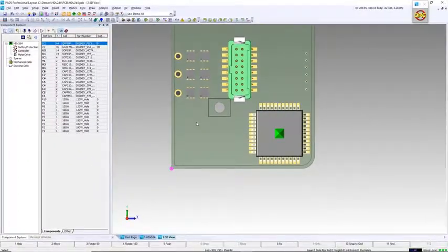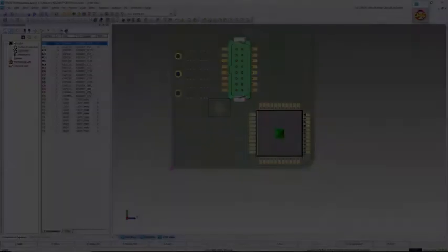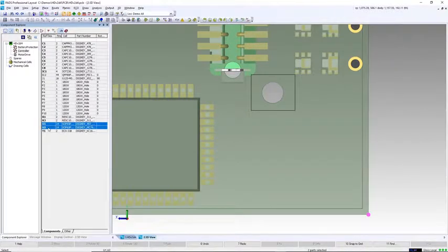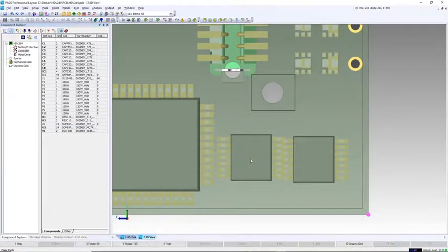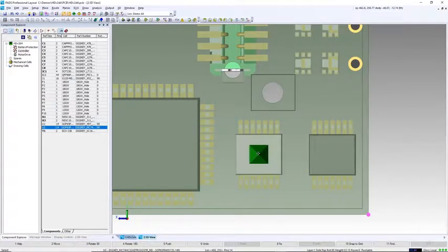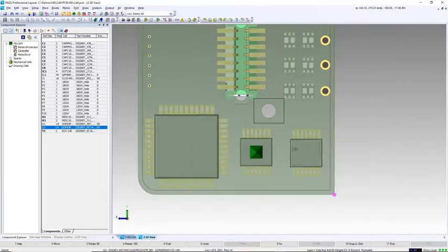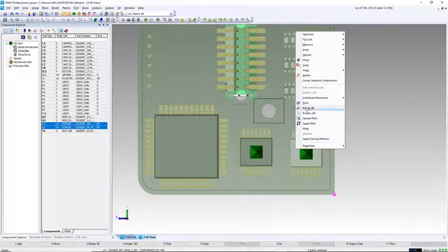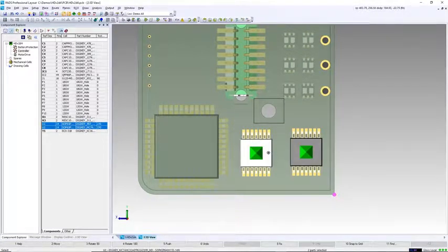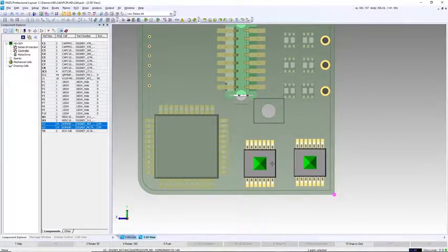We'll go ahead and place a couple more components here, this time on the bottom side of the board, but we'll do it in the 3D space. So again, I go back over to my Component Explorer. I'm going to pick 2 ICs in this case. You'll notice as I pull these parts onto the board, they already have 3D model assignments. This means I must have used these parts in another design. They're also turning yellow when I place them over the top of each other. This is indicating a clearance violation. We'll go into this in more detail a little bit later.